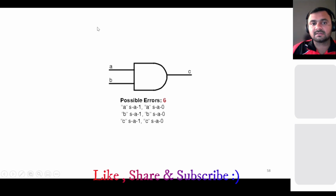This wire is connected to VDD, so this signal will always be at 1. It will not be at 0. That means if the fault here is stuck at 1, you cannot detect it, because it will always be a 1. To detect it, you need to force it to 0, and if you force it to 0, you need to propagate it, then B can be anything, so C will be 0. But since it is stuck at 1, it will always be at 1, so you cannot force it to 0. So this fault cannot be detected if it is stuck at 1.